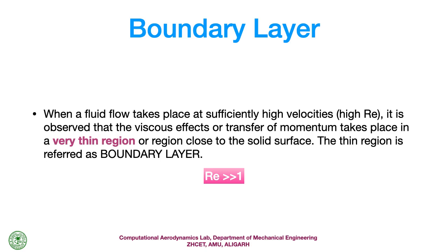Now, the whole concept of defining the boundary layer is that we want to see what type of equations we can solve in the boundary layer, because we know how to obtain the solution in the potential flow region. That means outside the boundary layer, we know how to solve, but inside the boundary layer, the whole Navier-Stokes equation is valid. Now, the Navier-Stokes equation is a two or three dimensional partial differential equation with a high degree of nonlinearity, which is difficult to solve.